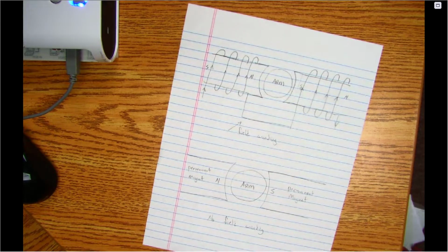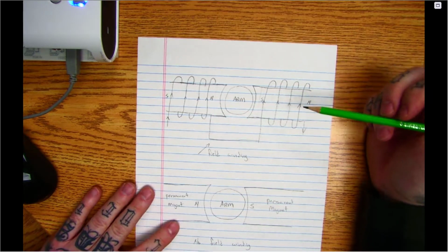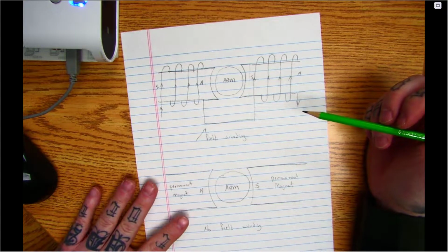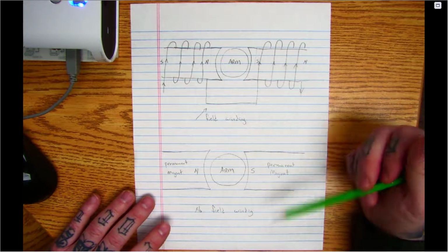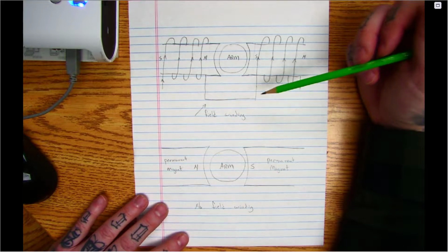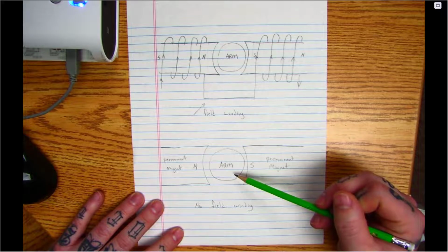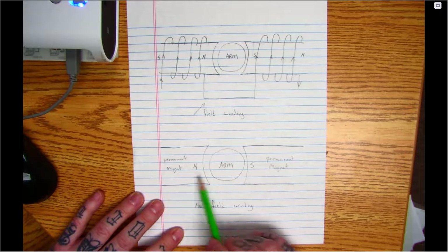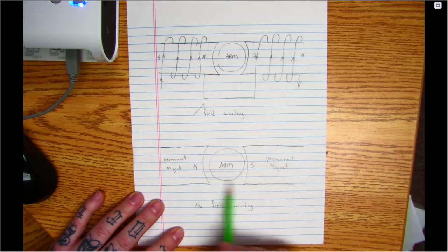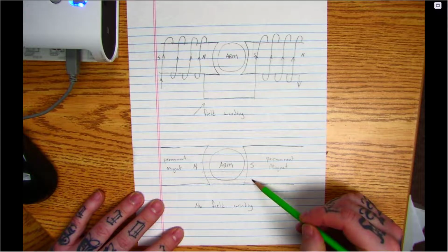I would usually draw this up on the board, but here's a breakdown to make sure we have an understanding of the difference between the permanent magnet and a field winding. If we had a permanent magnet and we rotate the armature through that, we're still going to generate a voltage. But we would lose any fine tuning or altering of the field if these are permanent magnets. There are lines of force going through here, but we can't change them. We can't make them stronger or weaker. So whatever output we get in this scenario, that's the output we're going to get.